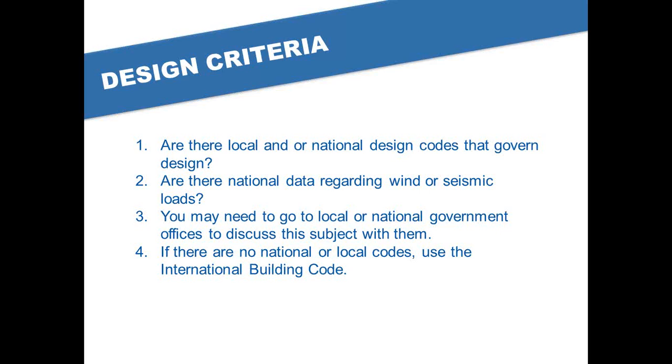One thing that throws a lot of chapters is getting the loading data for wind and seismic loads. Seismic earth movement is actually not that hard. If you just go to the U.S. Geological Survey website and type in something to the effect of international seismic movement, there's mapping for the entire world for seismic movement. So you can get that.